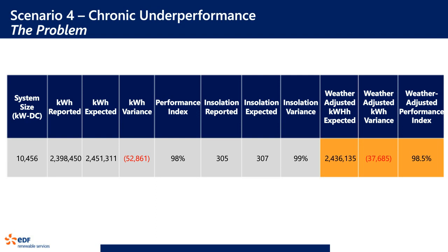And some of the problems when you're chasing these fine-grained performance issues come down to plant design and, frankly, sensitivity of the measuring device. In this case, this was a thin film plant that runs 6 in series, 4 in parallel, right? So what happens is we're running fairly low currents with a lot of inputs. And what we see is these were, for instance, 200 amp inputs or CTs, current transducers measuring the DC current, rated at 200 amps. But when you're trying to look for these individual problems, these quote-unquote 1% problems, that is often below the calibrated sensitivity of the CTs.